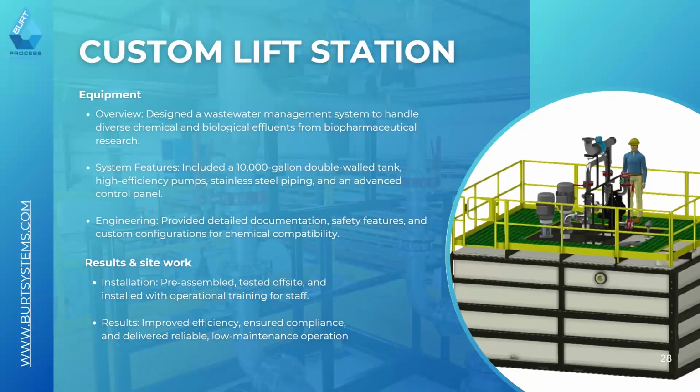I've worked on a few projects. The people have done very big ones. They've done 5,000-gallon lift stations that operate as both a lift station monitor and a pH system. What you see more of is people will take a pH, they're not sure that they actually need to do pH adjustment. They'll put a pH probe in the lift station to monitor it. So they'll do it more as a pH monitoring point that they can then tie a pH system into down the road, for example. But yes, it can be done.